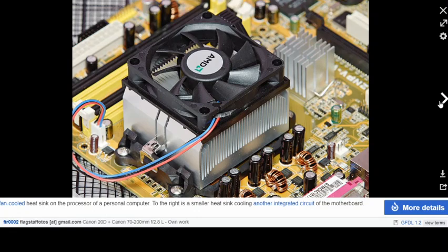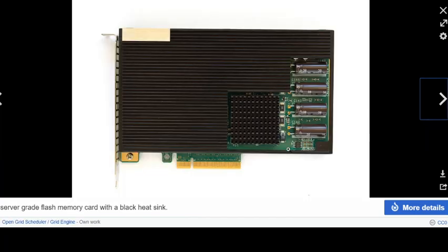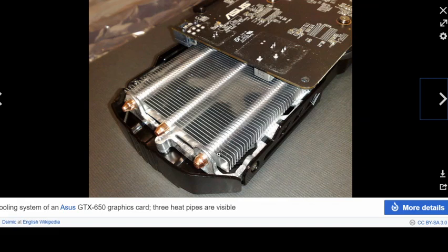More examples of the fins are these. These are multiple pin fins, these are multiple flat fins, these are also flat fins but with a varying gap between them, and this is a typical heat sink that is placed on a circuit board. The whole circuit board has a heat sink on top of it, and this is one of the processors that has a heat sink. And this is another example where this is a liquid cooled system where water can be made to flow through these pipes and the cooling can happen. So that is the example of fins that are cooling the systems.